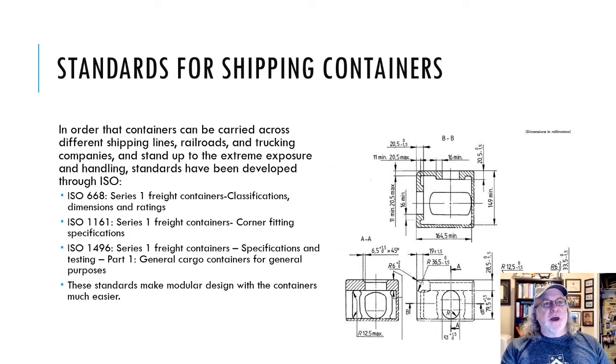Now going back here to this one right here, we can't use these loads. I was told I was arrogant by somebody on the internet because I didn't use these loads, but no, it's not arrogance. Once you start cutting up a shipping container, you change the strength of it. You can't go on the loads that come up in the specifications, even if it does seem kind of arrogant. You have to run the analysis.